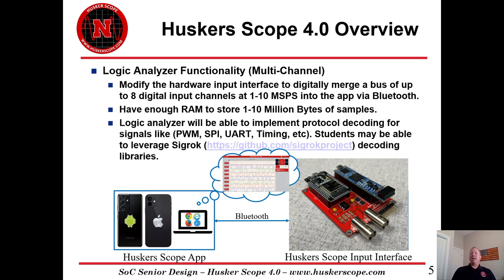We'll also look into being able to implement different protocols that you can find on SIGROK to be able to look at the signals and analyze them based on PWM, SPI, UART, and timing and that sort of thing. This currently is the state of the PCB. It will be modified this year, but it's at least a start.